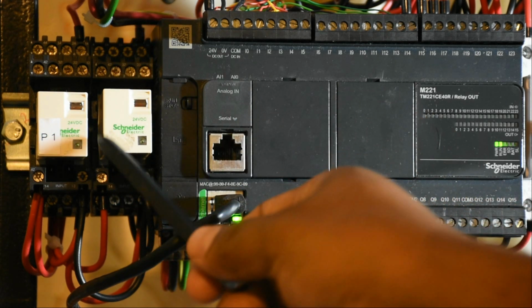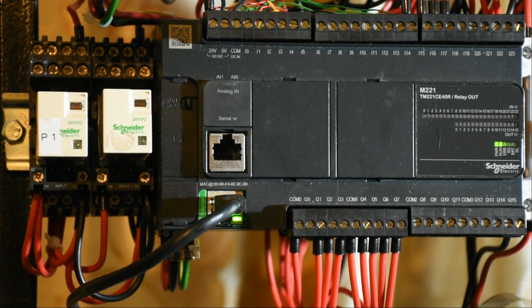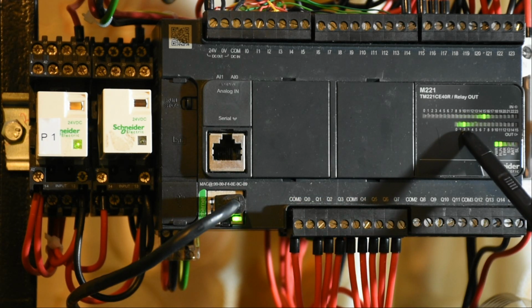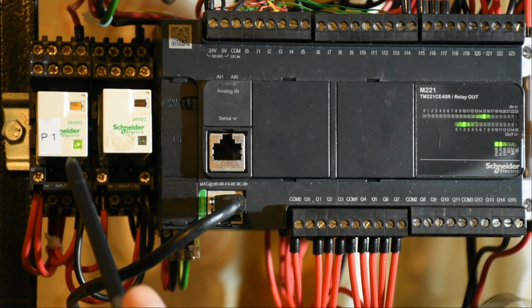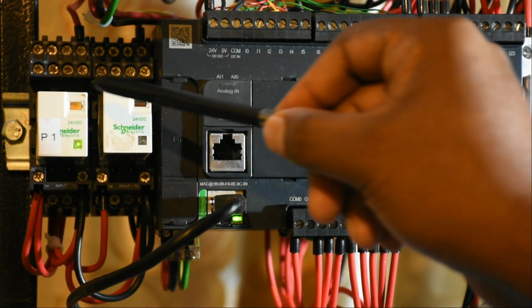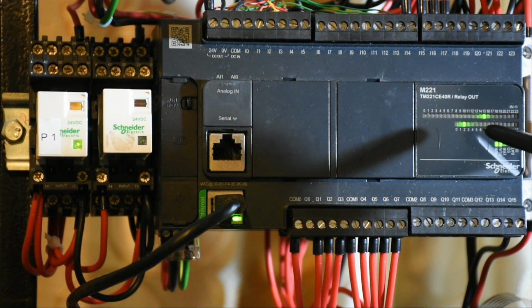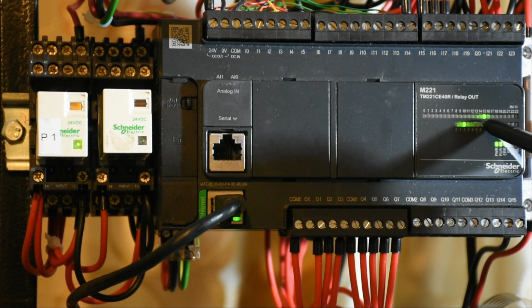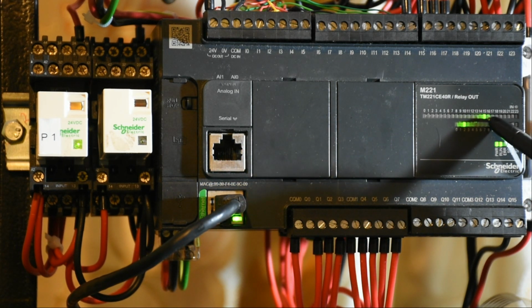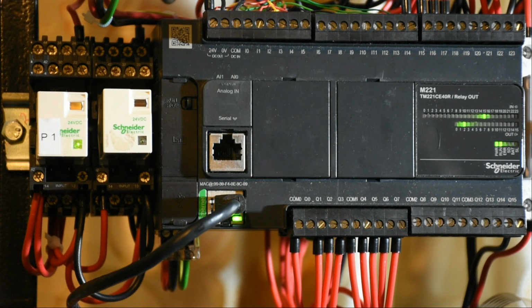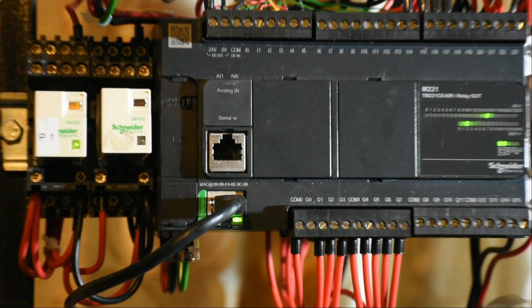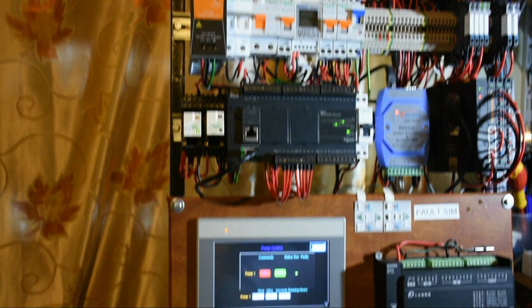This is the relay that the PLC will control whenever I give a command on the HMI. So right now it's off, so I press on. So you can see the output number 2 has activated and the relay number 1 has activated, and we have a reporting which is coming from this relay to input address here, which is on number 15, so that we can know that the pump is running via the relay feedback. And an overview back of how it is.